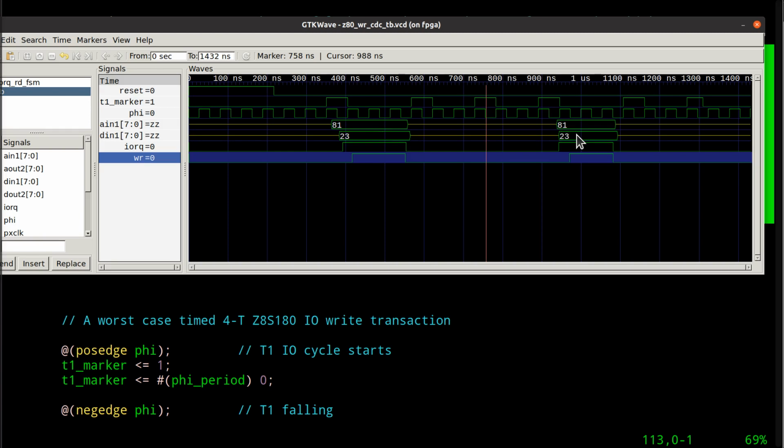If you did 2 I/O operations back to back in the machine instruction, an I/O operation would have an opcode fetch, an operand fetch, and then it would do an I/O operation. So it would take, there's the leading edge. Oh, let's do it this way, right? Put a border there, and then this is how long one I/O operation instruction would take at this clock rate on this machine, 540 nanoseconds in its entirety, if I do it using a regular old output instruction with an immediate operand to hold the port number. Okay, so that is why I wasted this time. You get a visual reference.